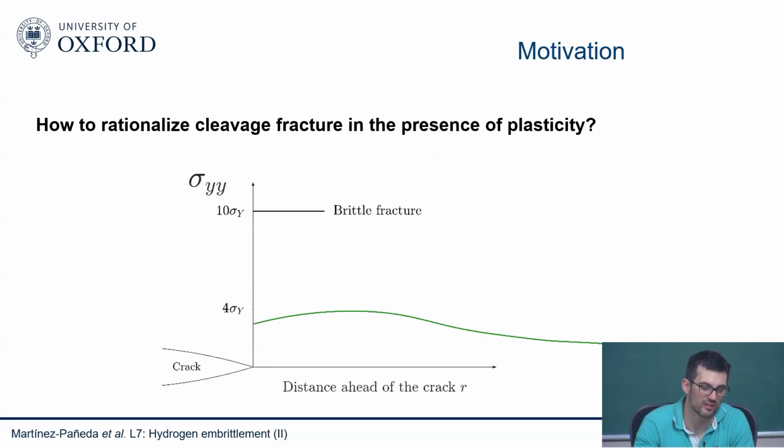And I should emphasize here that I'm discussing these fracture mechanisms in the context of the stresses. But in reality, as you know, fracture occurs due to an energy, right? Energy absorbed versus energy propagation. Otherwise, we'd have fracture at very low loads in linear elastic materials.